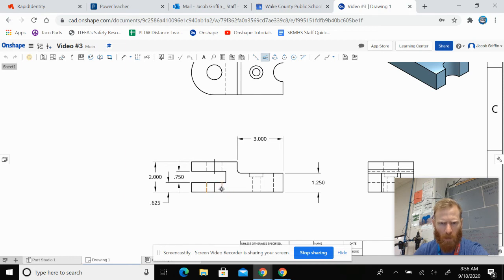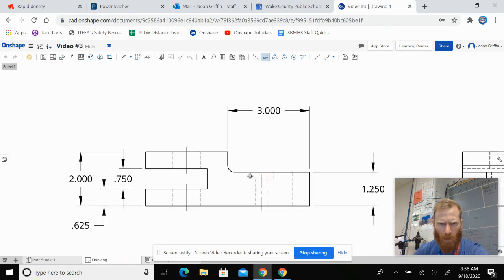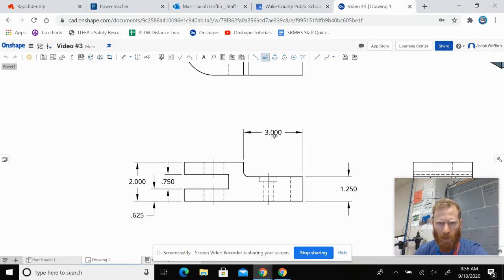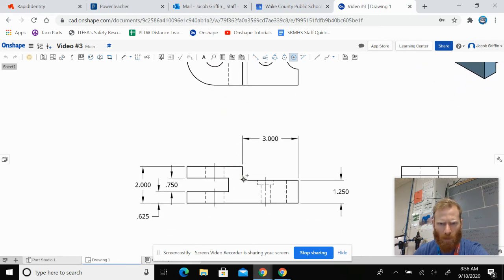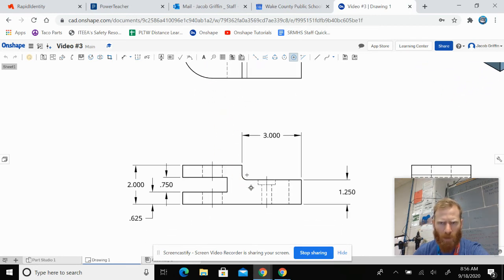They're not showing as a full center mark because it's at the same place where that arch becomes tangent with the sides. And so you have that solid line, and a center line is not going to trump that solid line. All right, let's throw in some center marks up here while we're doing this. Center mark on our arch, center mark on our counter bore, center mark on that. You can actually even throw in a center mark on a round over if you like.